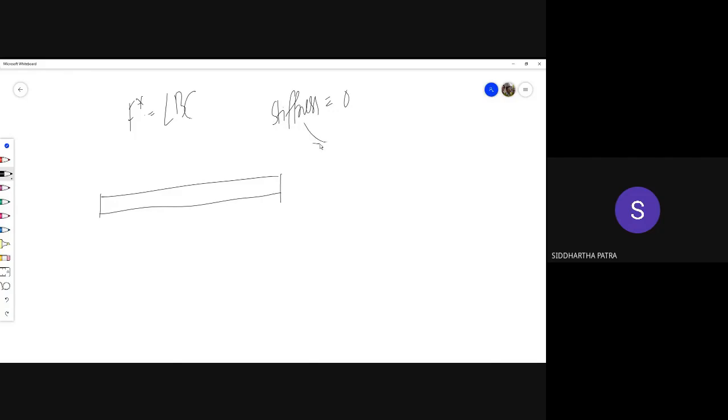Stiffness against bending. It just becomes zero when you reach that F star value. So imagine F reaches that F star value, and this cross section right here has completely become plastic, and it can no longer bear any additional amount of load. This given cross section has no moment bearing capacity.